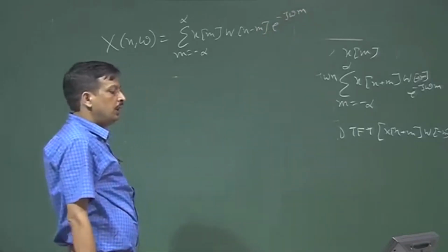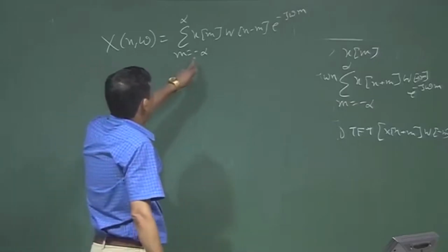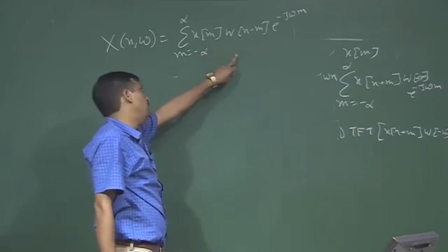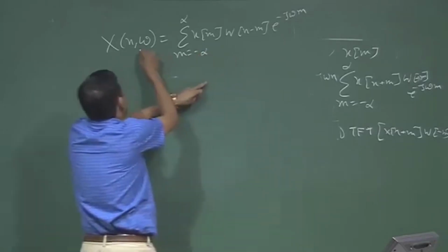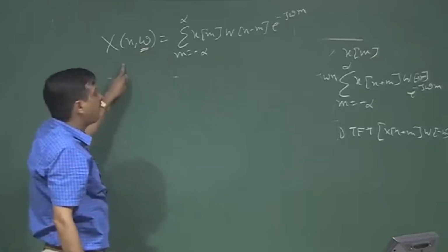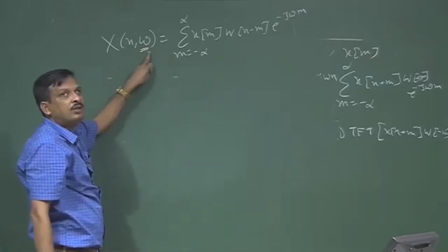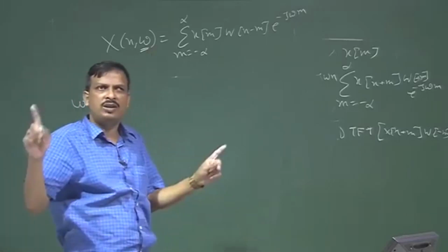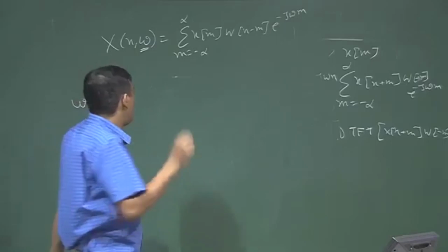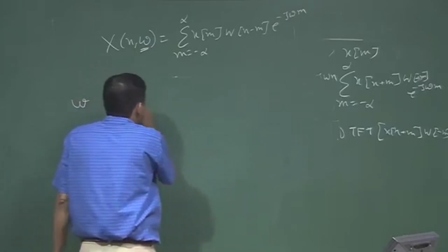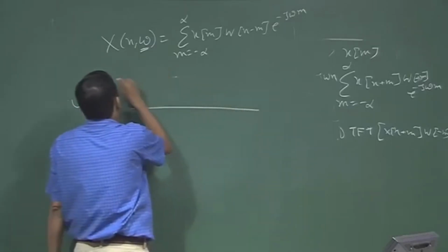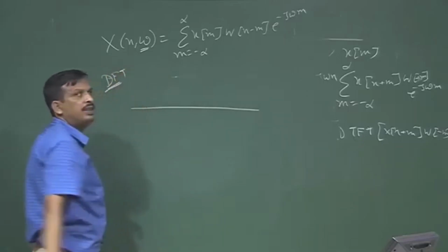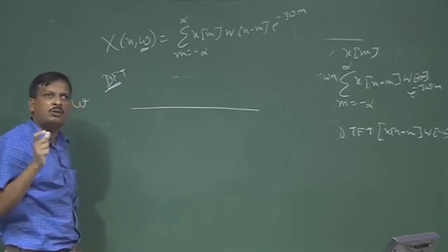This is the DTFT, the discrete time Fourier transform, so omega is continuous. Now I want to make omega discrete. How does omega become discrete? Omega is continuous in the frequency plane, so I have a frequency scale and I use the DFT, the discrete Fourier transform. Then the length of the discrete Fourier transform is involved.